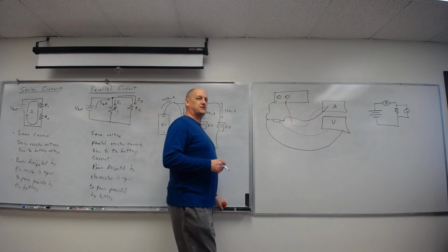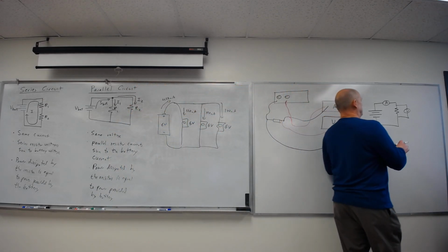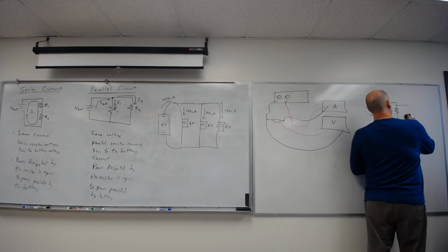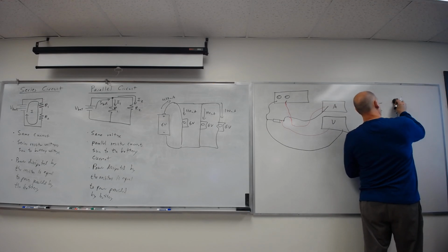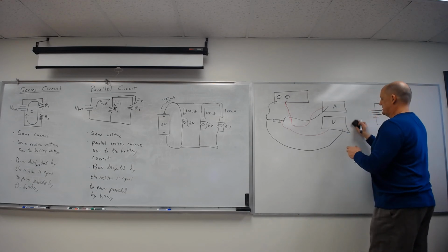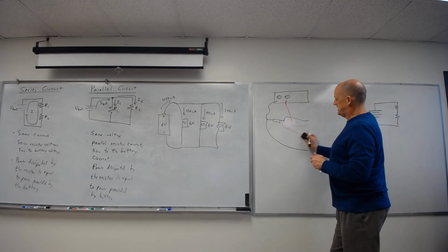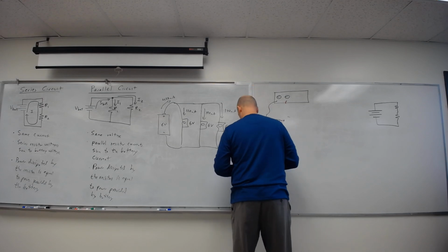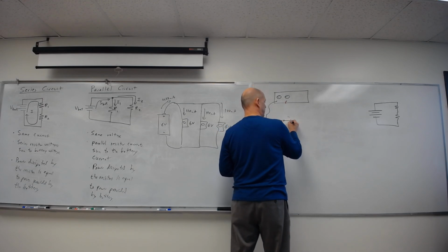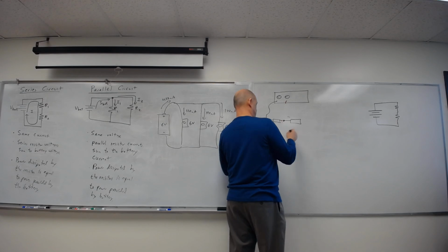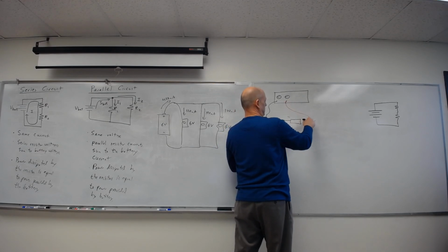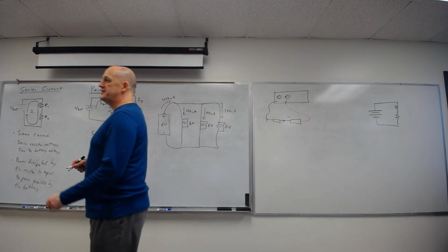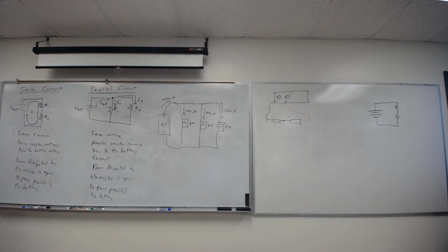So if I want to put 2 resistors in series, I'll add that ammeter later. I have to run out of one resistor and into the next. So if I'm going to come over here, take my little measuring devices out, I'll need to go get an alligator clip or something out of the bag to connect those 2 together. Now I go through 2 resistors in series, out of one and into the next, and I'll just flip them up with little alligator clips.